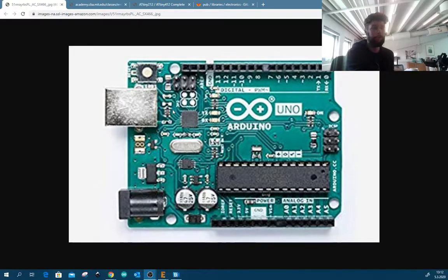This cycle we got new tiny microcontrollers, and they don't specifically need an ISP initially to be used. That's the main difference. It comes with an internal bootloader. That's the biggest difference between the ATtinys we had before and the ones we have now.